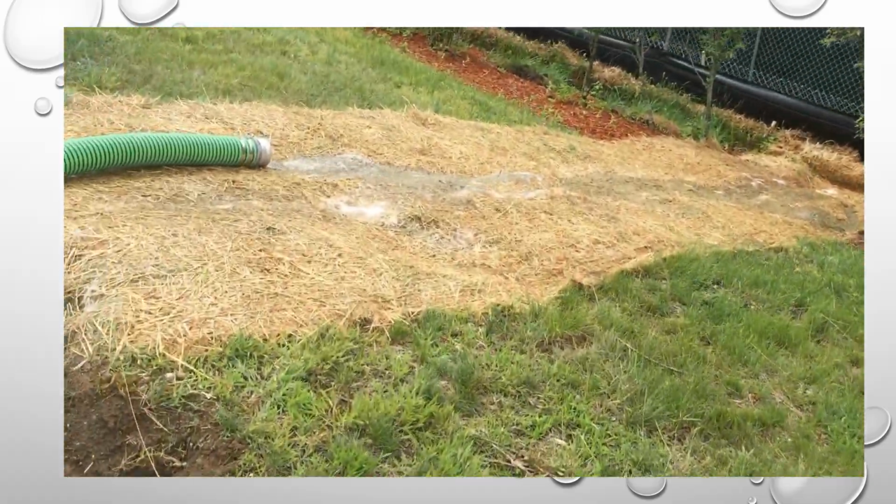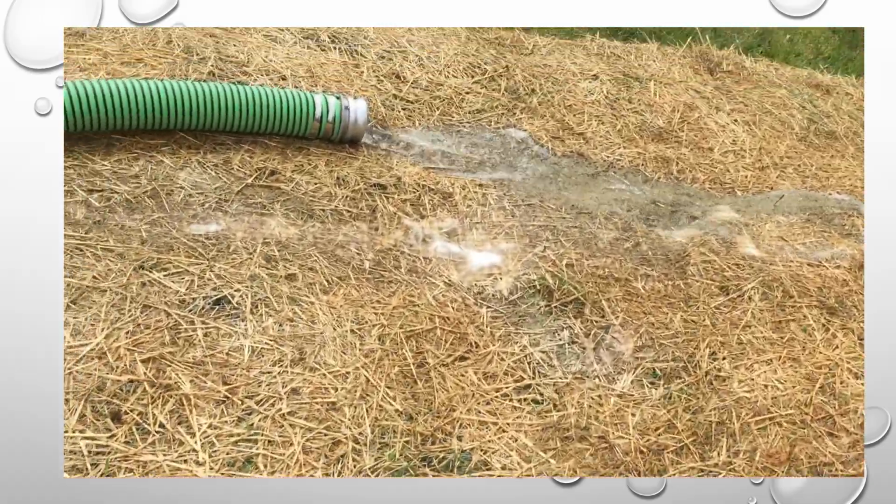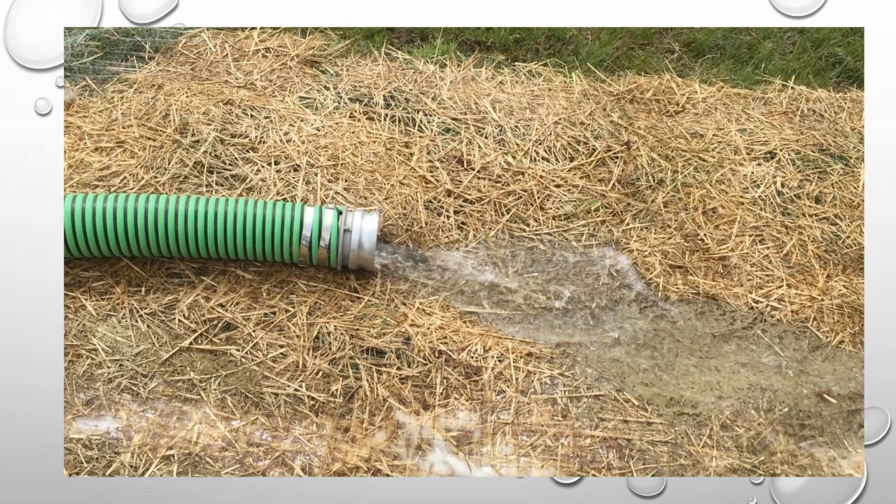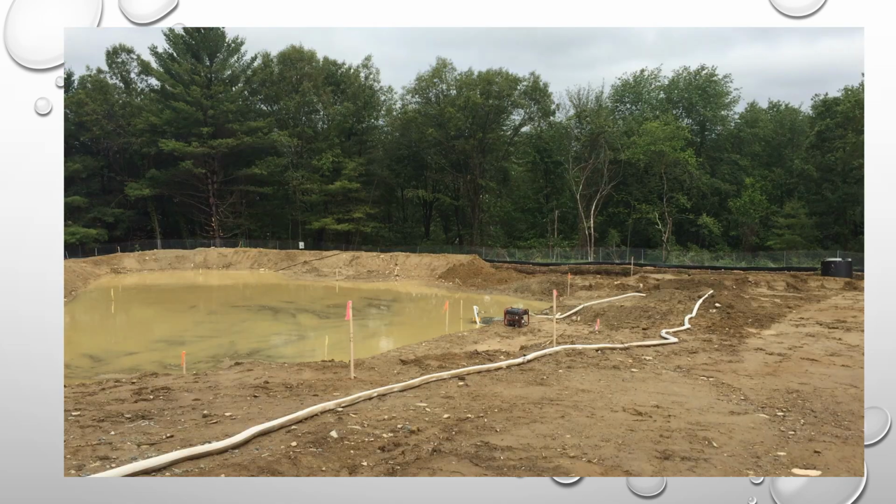And then that final hose adds the polymers in the water, but this final hose adds some additional mixing and reaction time. And you can see by the time it exits that hose, we've formed those flocks big enough where they can collect on that straw matting there. You can see the gray mass of flocculated particulates.